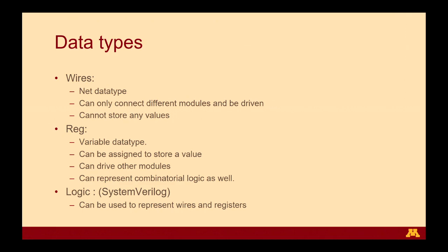There's actually a lot of confusion about when to use wires and when to use registers. In general, if you're new to Verilog and SystemVerilog, you can probably just use the logic data type. The logic data type was introduced in SystemVerilog just to remove the confusion between wires and registers, and in most scenarios, logic can directly replace both. So if you're getting confused about when to use wires and when to use registers, logic is probably your safest option.